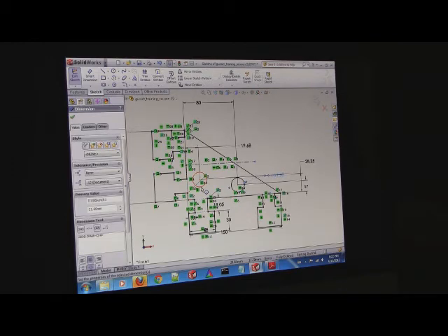Interesting tidbit. Yours is not fully constrained. Can I see? Yeah, why do these keep being blue? Hit control. So if they are blue, that means they are not constrained? Yeah, I'm not sure. Let's figure that out later. And then the only thing you have to do is trim right there. Yeah. And then you're good. Okay, so everybody got two holes?